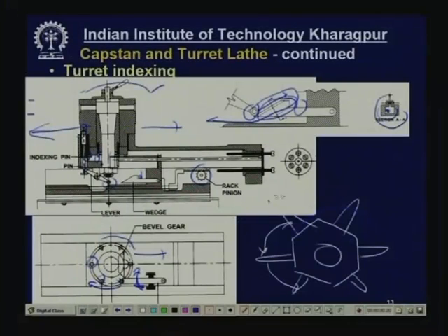Whatever you do, what will be the length of travel or end of travel? That will be decided by when the screw end strikes here, the stop. This cannot be moved further either manually or automatically. The clutch will open or the person will feel it. So, this screw decides the end of travel of the cutting tool. Now, there are many cutting tools which require different lengths of travel. For different lengths of travel, 6 different screws are mounted here like this, and when this turret is rotated,